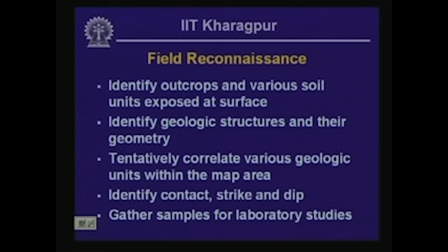Then the responsibility lies in identifying contact, strike and dip of these different geologic units, and also samples must be gathered from the outcropping units for laboratory studies, because although tentatively various geologic units might be correlated with each other, confirmed correlation can be available only based on some firmer, more precise information that can only be available from laboratory studies.